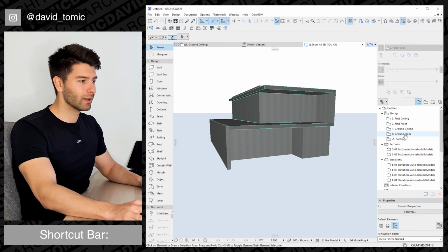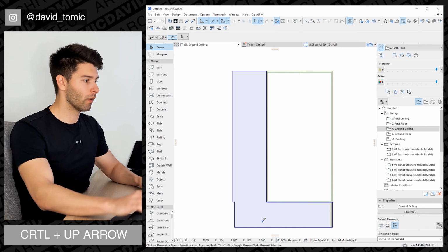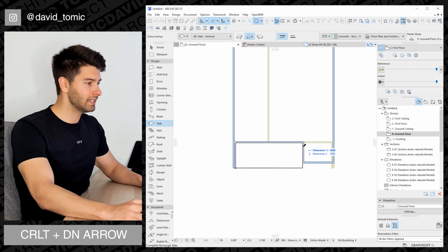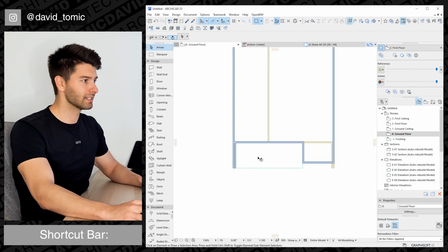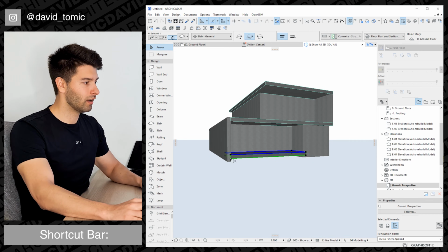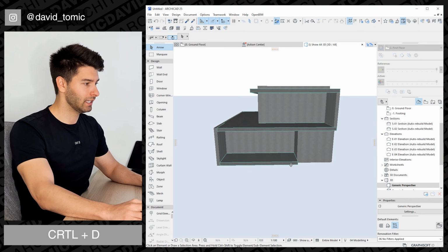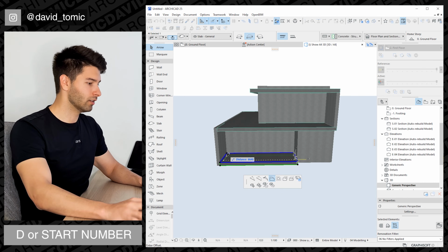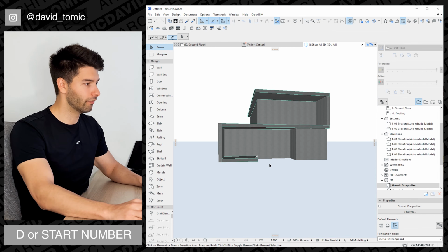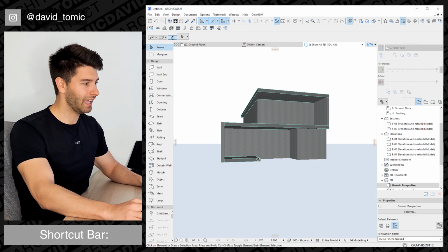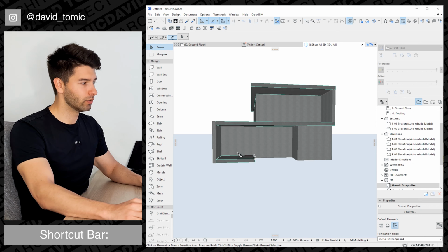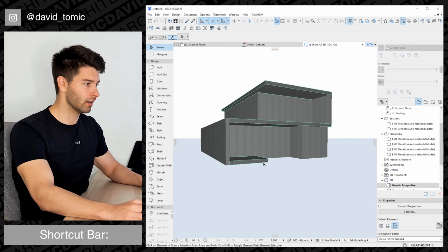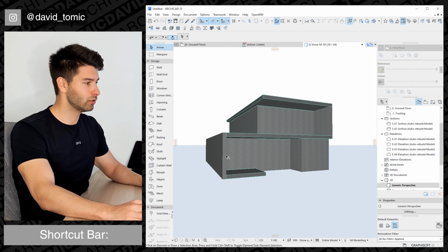To finish this off, I do want to come back into my ground floor, go up one level and select that concrete floor, then go back to my ground floor and simply draw in our concrete slab at the bottom. So we tie that back in completely. Now it probably doesn't need to be that long, probably can go back in to only about 3 meters instead of the full size. So we have a sweeping S look. That could be a step up to a little platform, a little tree, whatever we decide to do in the elevation design. Now let's focus on this actual elevation of this 2D house.